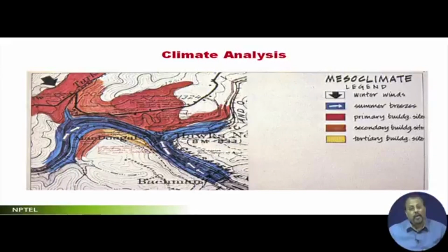If there is any wind shadow, that means an area which was supposed to get the wind, but because of the contours and the profiles you don't have that, so wind shadow zone. Or is there any wind tunnel effect, which is regulating the entire wind gently flowing but suddenly entering into your site through some crevices, and ultimately the velocity increases, there is a wind chill effect. So these are the things which you are going to check with respect to your site.